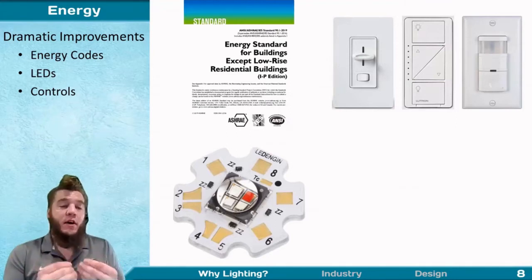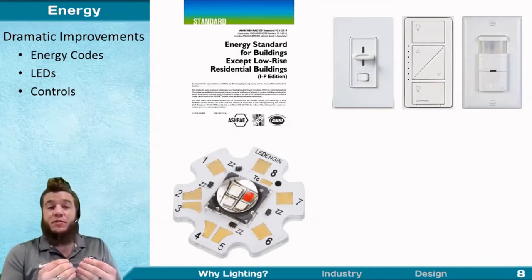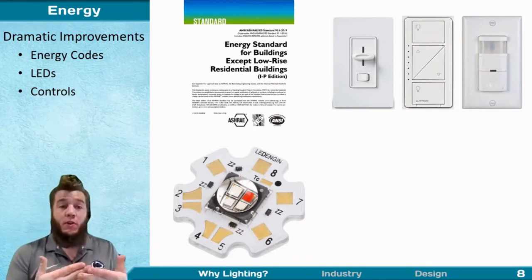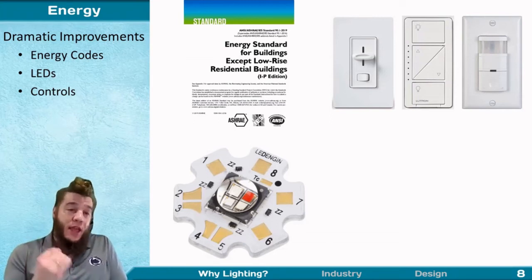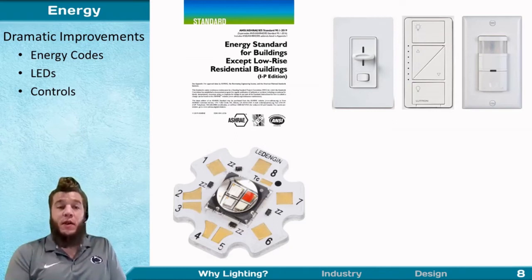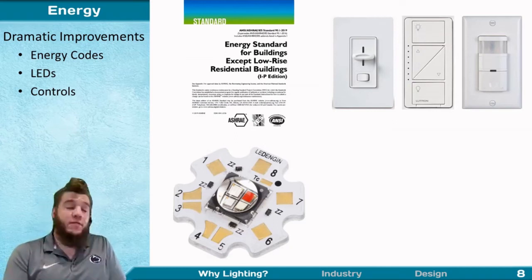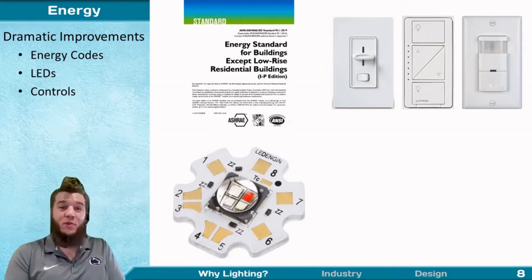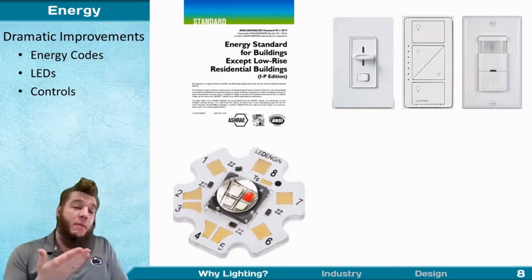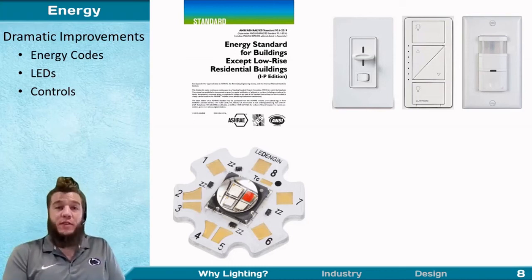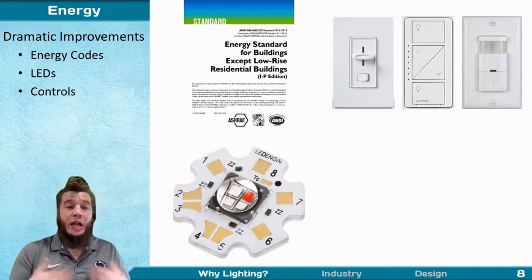So LEDs are an inherently digital device. They come with a microcontroller on board. They basically don't function without one. And so they're inherently controllable light sources. But without a lighting designer, oftentimes you just end up with an on-off switch or analog dimmer, which is wildly inappropriate for something that's controlled with a digital wave. So controls are a big part of how we really realize the energy savings by making our LEDs intelligent and responsive to the actual needs of the occupants of the spaces we design for.